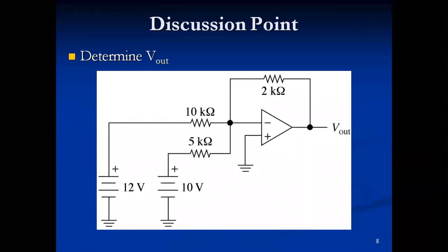Okay, so now let's look at this first one. When we have this again grounded, we are forcing this node to be 0 volts. Can you tell me the new output voltage for this configuration? We're just going to take 1 minute to do it. You're doing what we did before with the voltage difference divided by the resistor. Then you're going to find the current through the 2 kilo ohms. Remember, you have 2 branches now. And then you'll find V out.